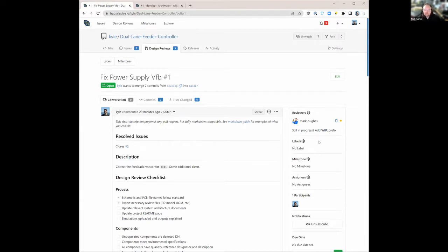Other things: did you read the data sheets? Did you implement the required things correctly? Like if you're doing a power boost circuit, did you correctly calculate the resistor divider for the feedback pin? All sorts of stuff like that. So let's hit it, man.